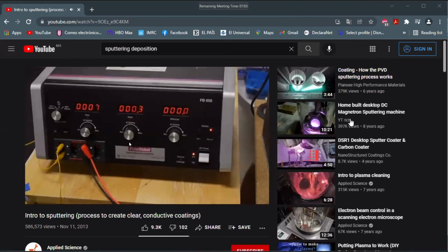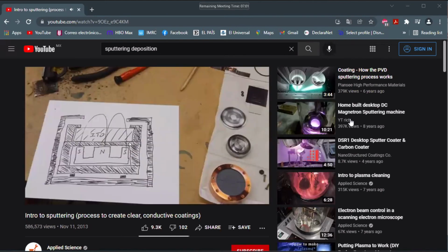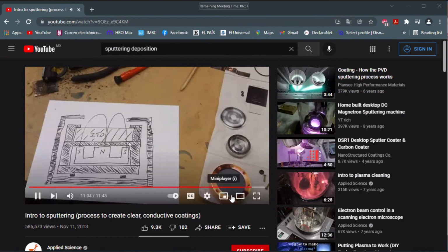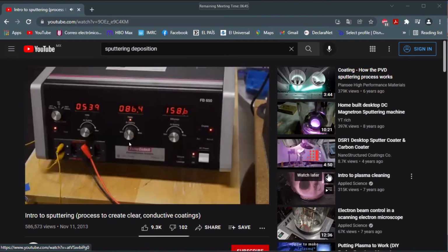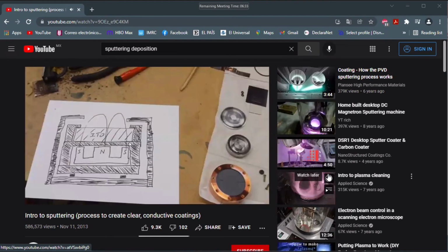Besides all the stupid safety interlocks that make it difficult to use, the supply goes into its current limit condition kind of too quickly, and it's hard to get a consistent voltage current out of it. It is nice that it has a constant power function, so you can actually set a desired wattage and then play with the chamber pressure, and it will balance the voltage and current without exceeding that power limit. However, I think for future experiments, what I'm going to use is just a microwave oven transformer with the standard diode and control it with a variac.